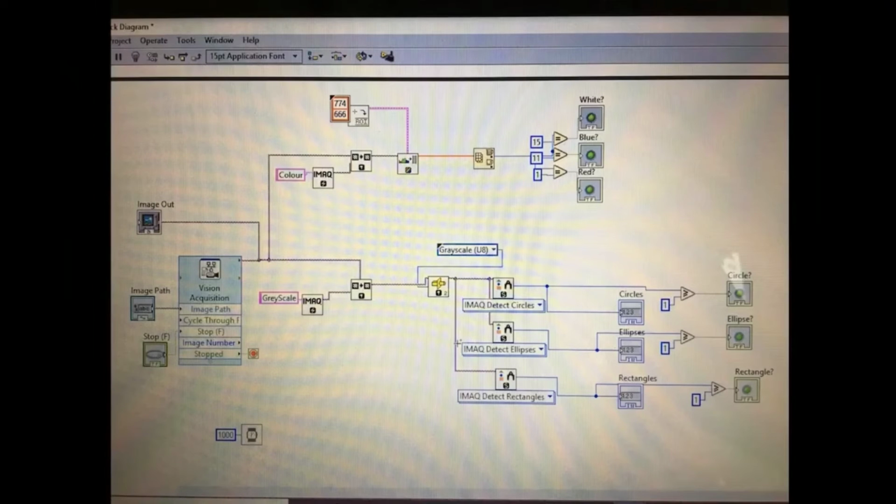And then what Color Learn does is it returns a one-dimensional array of all color values, and whichever color value is the highest, so each color is indexed. So for example, red is index 2, and so if red has the maximum value, then the max index would be 2. And so you can see in this case red was actually 1, white index was 15, blue index was 11. So we search the array for the maximum index and compare it to the known indexes of each color, and then that sends a signal whether or not it's red, blue, or white.